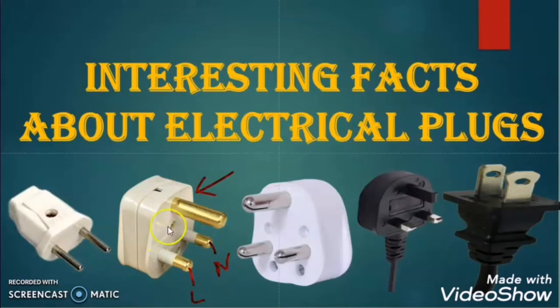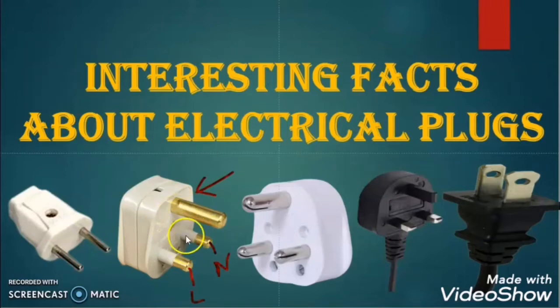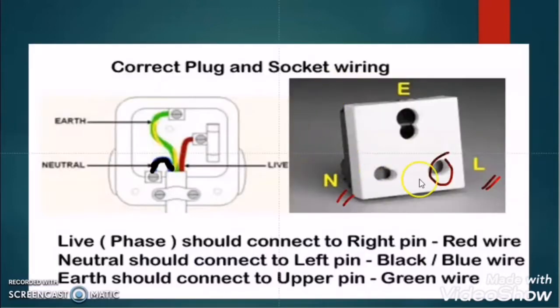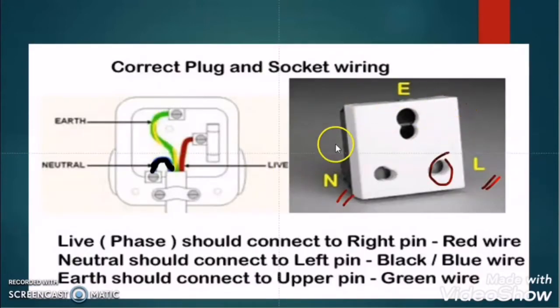But this is opposite for the 3-pin socket. In the case of a 3-pin socket, the right terminal is the line terminal and the left terminal is the neutral terminal, just opposite of the plug. To remember which side is line and which is neutral, don't try to remember both the plug and the socket. Just try to remember one of them, either the plug or the socket.